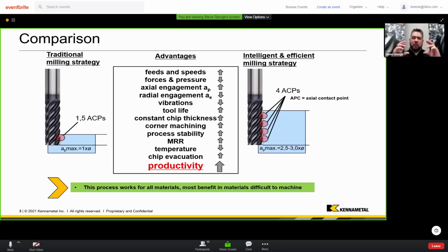The depth of everything starts to become very important to me as I analyze this, working with somebody. If the depth is such that I'm only going to use half times the diameter of the cutter, maybe 1 times, maybe even 2 times, depending on the type of tool, that starts to get me thinking that maybe a traditional approach could be better: take a big radial cut, because I don't have the advantage of going with a deep axial cut, right?